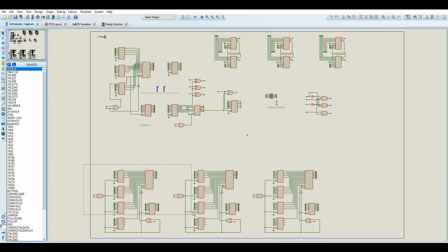And again, we have the same repeated pattern of 3 for the address selection logic going into the RAM, and this is whether or not to output the read information from the RAM, or to write the external data bus value to the RAM, and all of the associated RAM selection logic here and here.